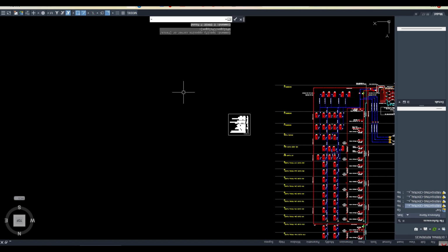Now, up to 15 meters, we call it a low rise building. From 15 meters to 23 meters, we call it a mid rise building. Then from 23 to 90 meters height, we call it a high rise building. And 90 meters and above, we call it a super high rise building.